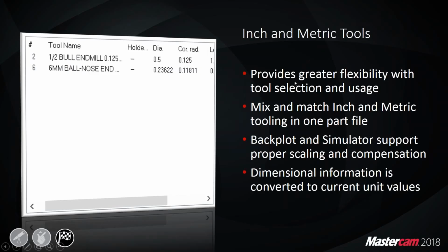We now have additional support for inch and metric tools. Before, in Mastercam, you would have to convert a metric tool into the inch library and then bring it into Mastercam, or you'd have to create a tool and type the metric value into an inch tool. But now you can open up any inch or metric tool library and have it pull right into Mastercam.